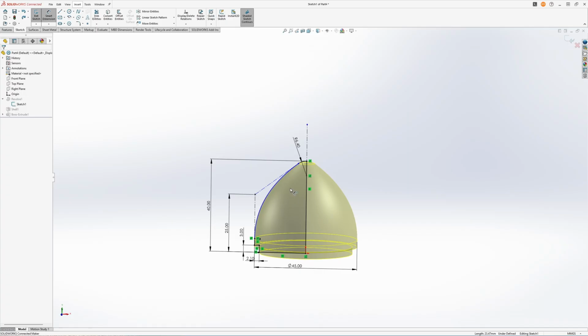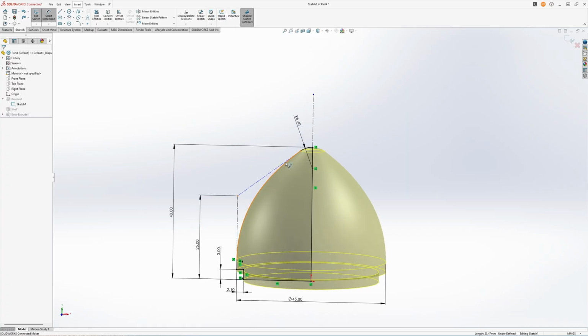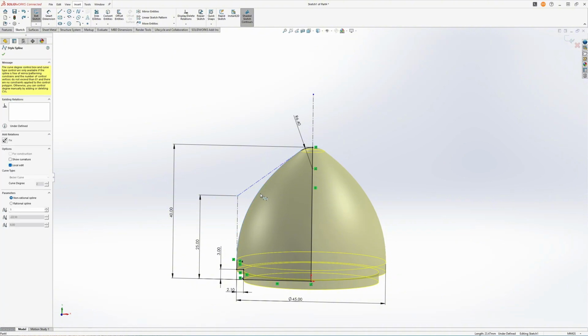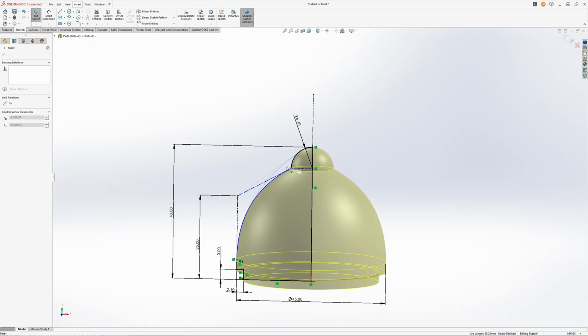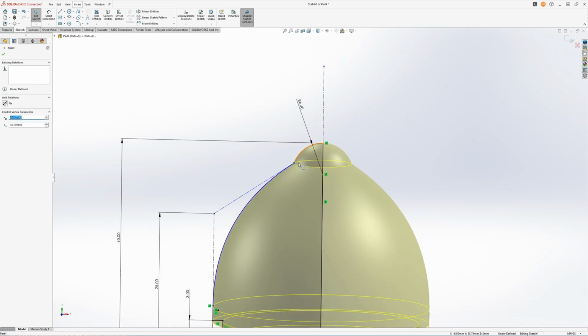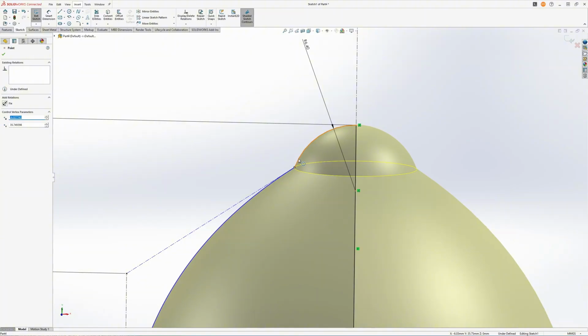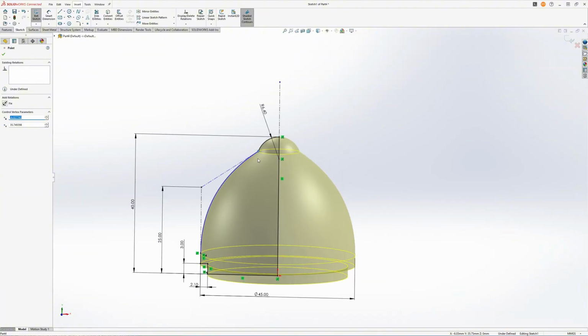So another way to play with the geometry is, now that you don't have a dimension, you just drag it. You see what does it actually change. You see that it changes here. And that also actually tells you something else. We thought that we had the tangential continuity, but we don't, because it can actually break in these two lines. You see it goes like that. So this is another way to check that your model is drawn up as you were expecting, by just dragging the blue lines. So let's click on this one and click on that one again.